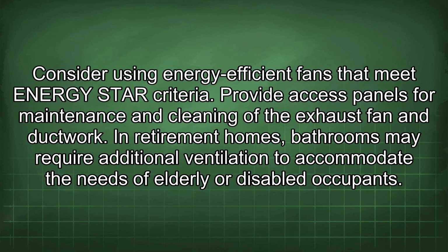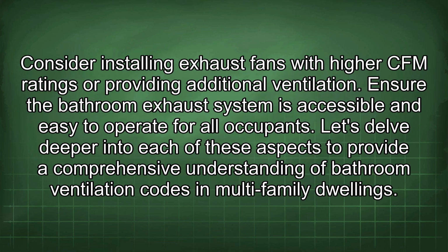In retirement homes, bathrooms may require additional ventilation to accommodate the needs of elderly or disabled occupants. Consider installing exhaust fans with high CFM ratings or providing additional ventilation. Ensure the bathroom exhaust system is accessible and easy to operate for all occupants.